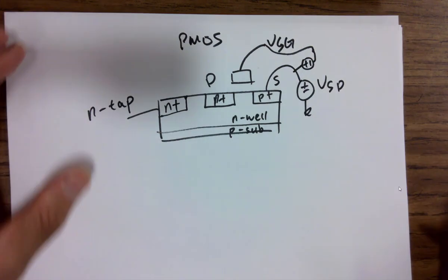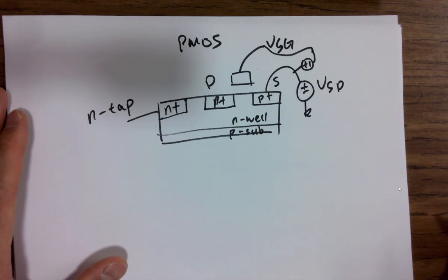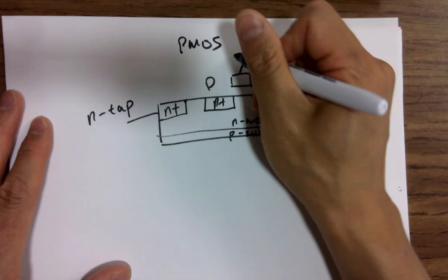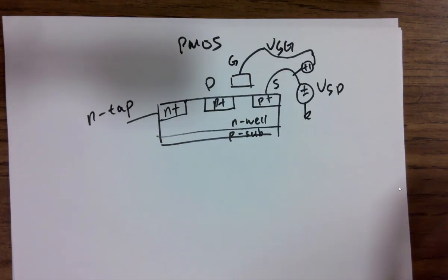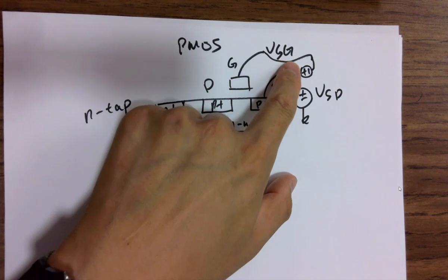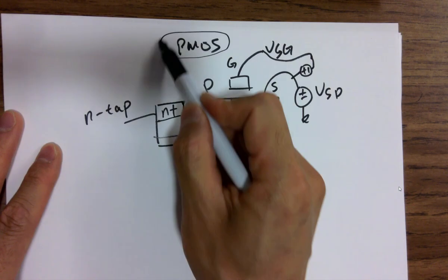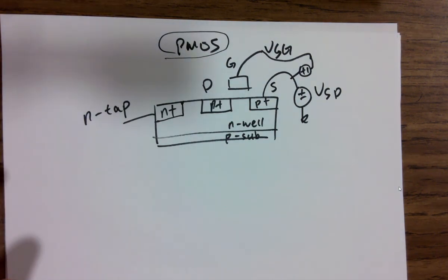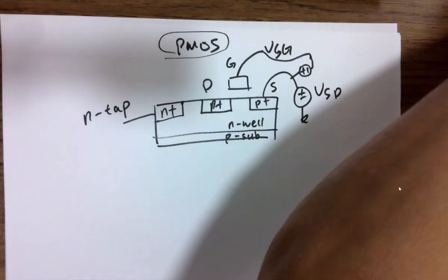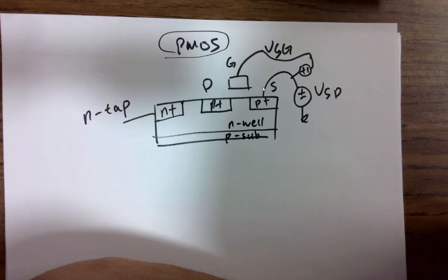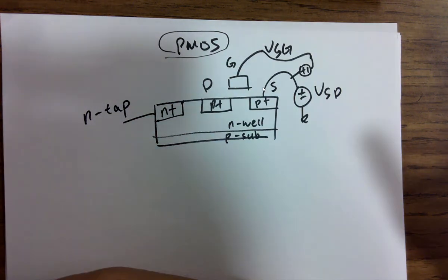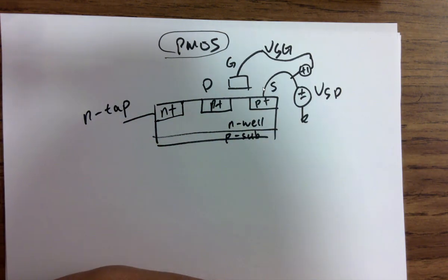Any questions on this? Isn't the direction of the voltage flipped? Instead of going from gate to source, you're going from source to gate now? Yeah, gate to source becomes negative, so we prefer SG. You can see it differently in different textbooks. Sometimes they use VGS for PMOS as well, but it becomes negative. It's confusing people. So it's just flipped, but no other major differences.